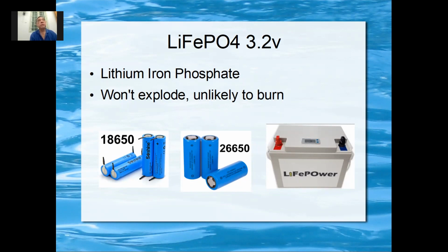Normally they use 4 pieces. If they use 4 pieces of lithium iron phosphate battery, you take 3.2 times 4, which gets you 12.8 volt. But if you use lithium ion, it's 3.7 times 4. So the voltage will be higher. So that is a difference.